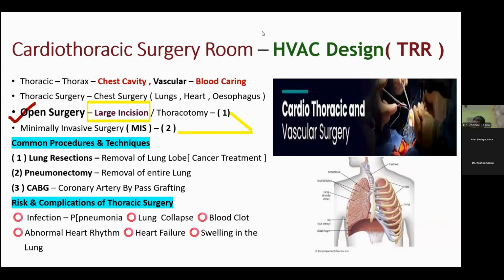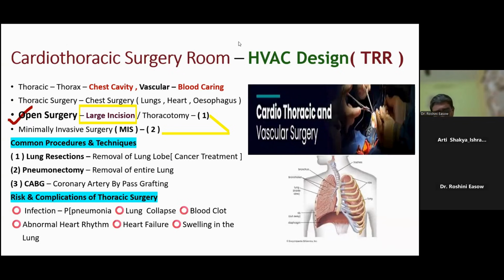It should actually be called an isolated low pressure room. You cannot keep somebody in a negative pressure. How does a negative pressure develop? Your supply pressure is less than your exhaust, so naturally there will be a vacuum. It's a low pressure. It is not good.